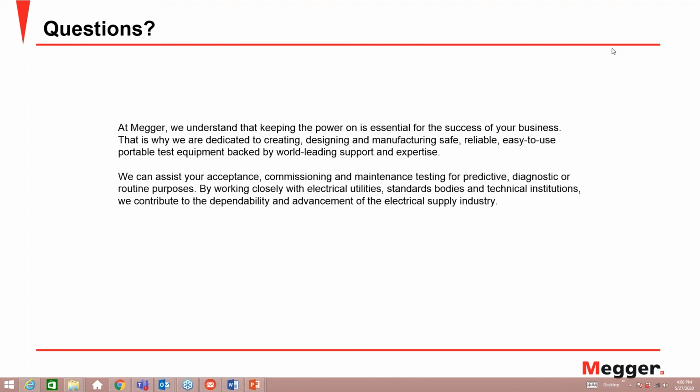So again, when a manufacturer approves the equalization of that particular model of battery, they typically would recommend it less often, or again, some manufacturers will say in the manual that this equalization is not recommended for that model. So in summary, just make sure you check the maintenance manual for the battery in question.